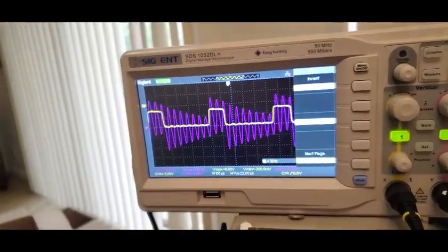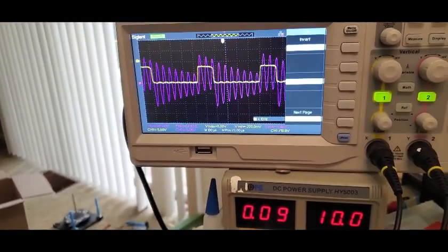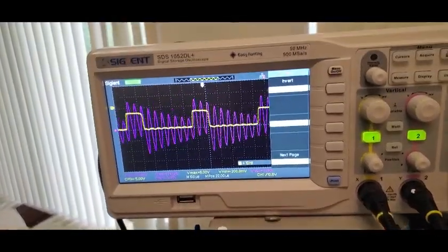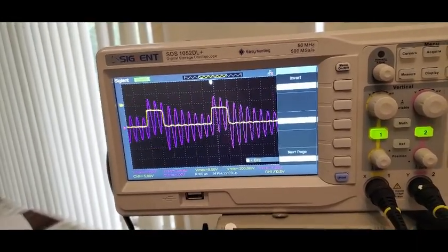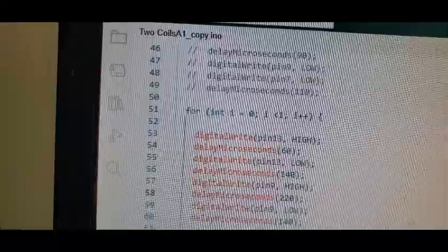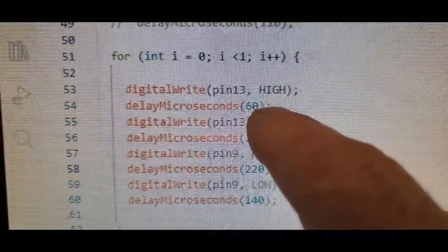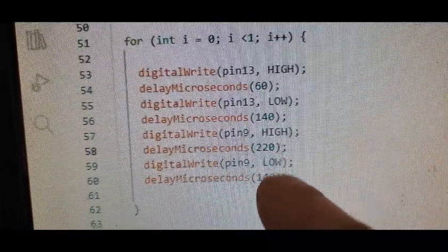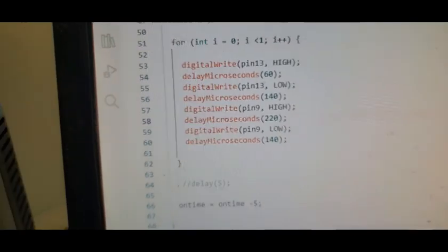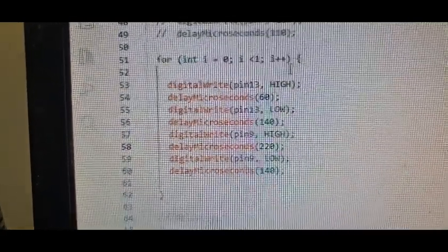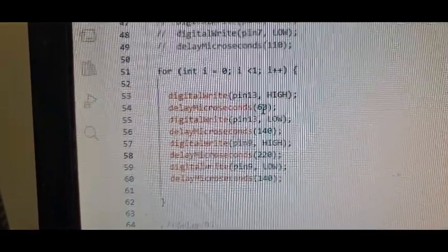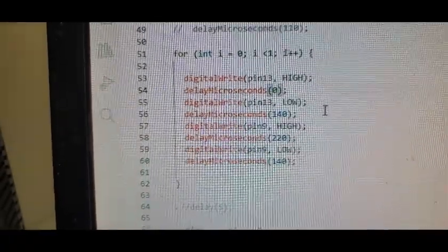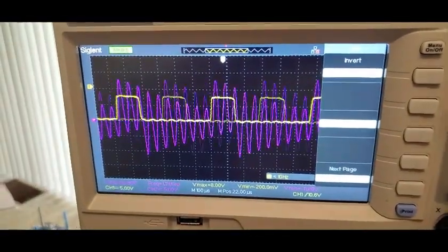Now the interesting thing that happens here is, let's see if this works, because sometimes there's other oscillations. I don't know if it's oscillating with ground or what it's doing, but sometimes it doesn't go as I expect. But let's see if this works. So we've got pin 13, and that's where it's just going through the resistor, and then that shuts off, and then this doesn't do anything, but it lets the SSRs rest for a minute. It's only 89 milliamps, I think they're half amp relays, so we can go up to, let's say 80, and let's see if it does what it was doing before.